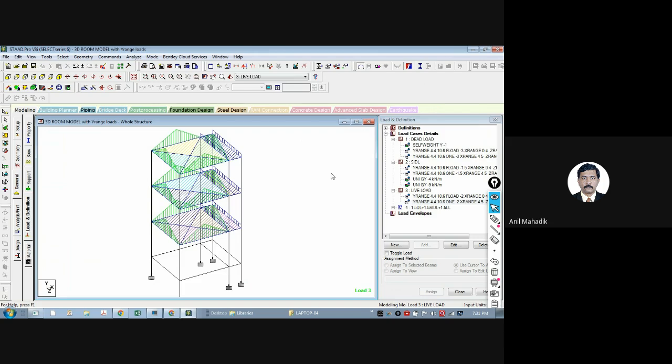So you may be understanding that if you want to prepare any multi-story building model, first define only a single floor, assign the properties, loads and everything, and then just copy it. If they are the same, copy; if they are not the same, then change wherever there is a change. There is a possibility that there are some additional beams on the second floor, so you just add those beams by using insert node and change the loads for that portion only. All other things are the same.